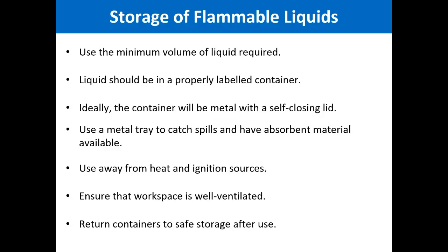Okay, what are the safety precautions for storage of flammable liquids? Obviously, you need to make sure that you use the minimum volume of liquid required. Don't store any extra flammable liquid on your site unless it is necessary. Liquids should be in a properly labeled container. The container should be metallic with a self-closing lid. Metal drip trays should be used to catch the spills. Store or use flammable liquids away from heat and ignition sources. Ensure the workplace is well ventilated, and return the containers to a safe storage area after use.